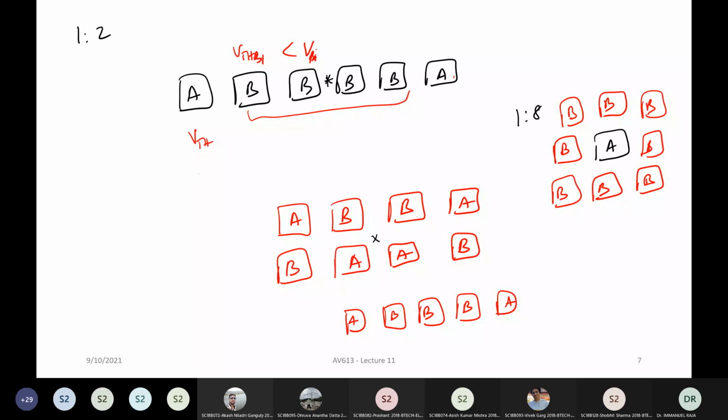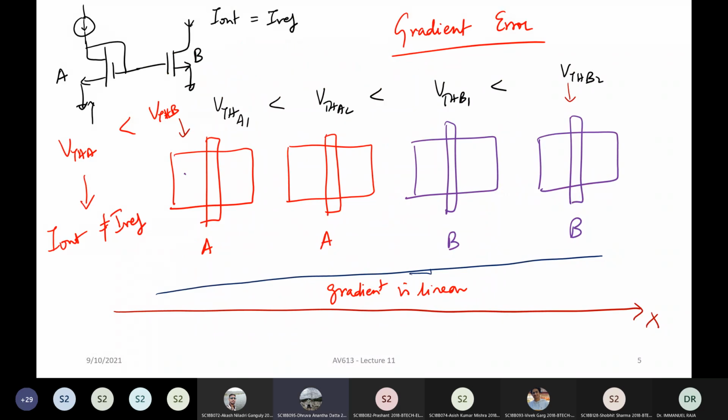When you're running simulation, even when you do layout, you'll do what is called layout parasitic extracted simulation. In schematic, you assume all the wires are ideal, right? If you take this current mirror, you have a lot of wires, all these connections. In schematic, it's an ideal wire. But when you do layout, all these wires are strips of metal which have some resistance and some capacitance, both to the substrate as well as to adjacent metal layers. Now all those effects are captured by what is called parasitic extraction.